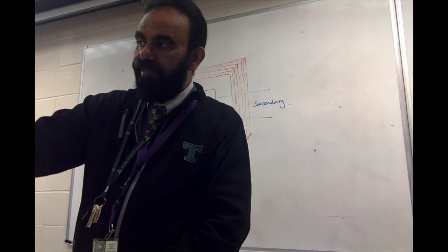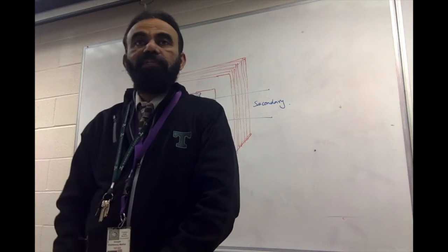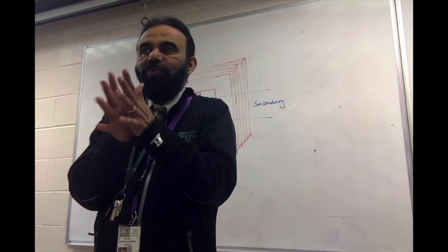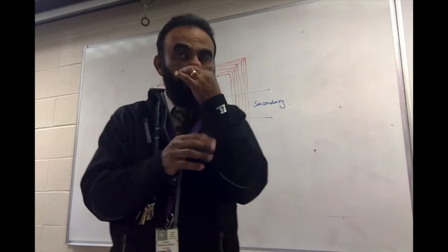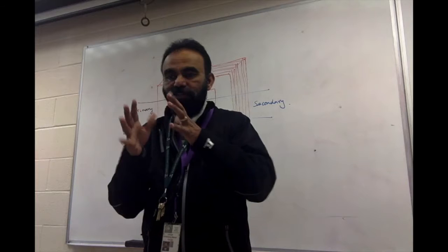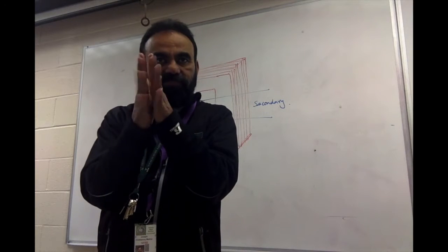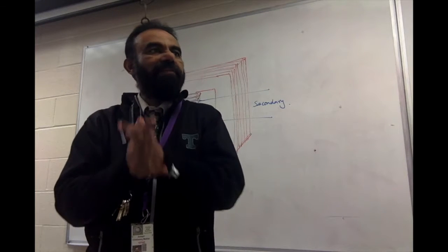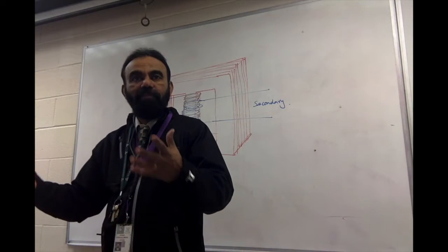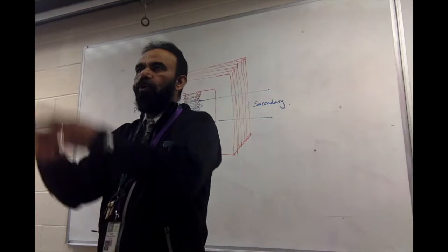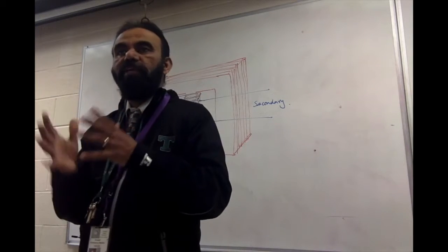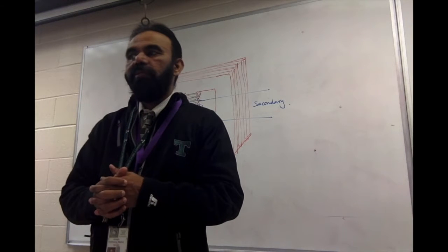I think they have even welded one of the sides, to make sure that it is not going to vibrate. You don't want it to be loosely packed, because if it's loosely packed, what will happen is when the magnetic flux is changing, those metal sheets will start chattering. They'll start vibrating. You know, when I was turning that thing on, it made a lot of noise, right? The main reason is because the windings and the core are all loose, not too tight. That's the reason why it was making a lot of vibration sounds.